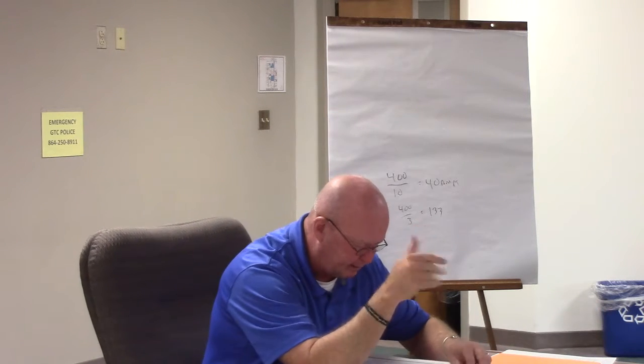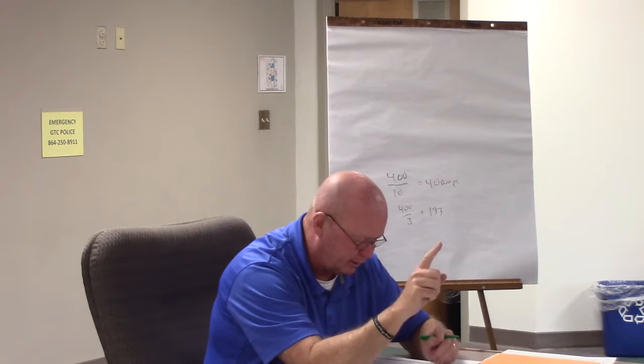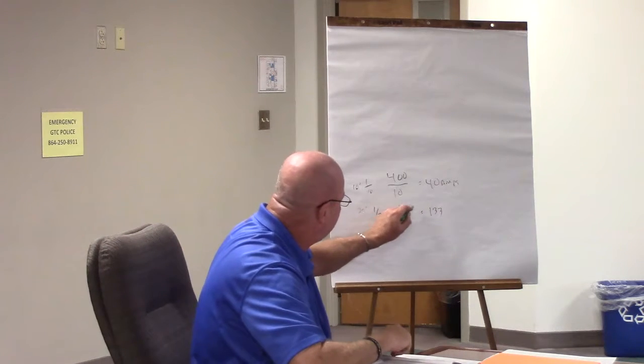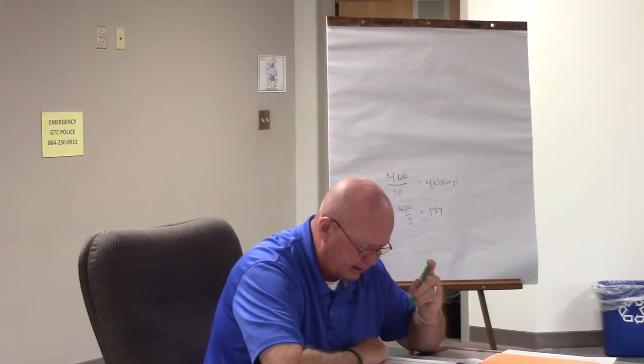Okay. So if we look at our other bullet, so that's the key one. I would mark that one right there. That, to me, that's the important thing. 1/3 of the capacity of the overcurrent device. So this is their overcurrent device on this example. We'll do some examples here in a minute. Bullet point number 3 says what?